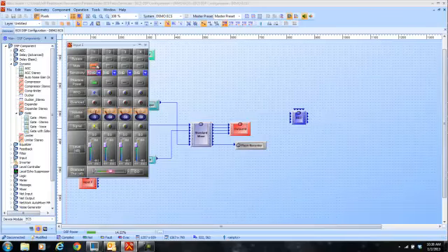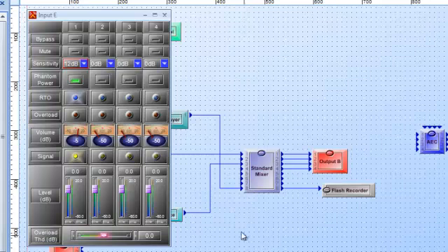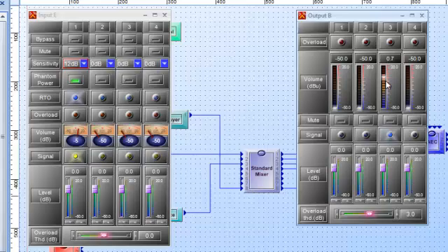Alright, check 1, 2. I have a reference microphone, so I have phantom power turned on for that one input on my microphone. We will open up the output, so we make sure that, yep, here we are on output 3, because I just got it straight through the standard mixer, and you can see our output right there. That's a little hot. Let's move that down about -3. Check 1, 2. There you go. We're running about 0 dB, a little bit less than that.